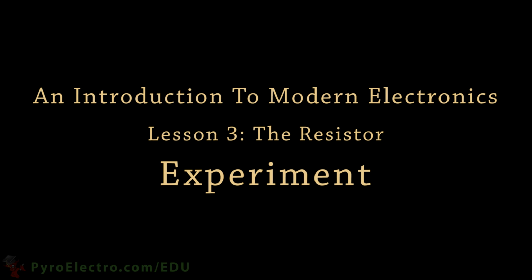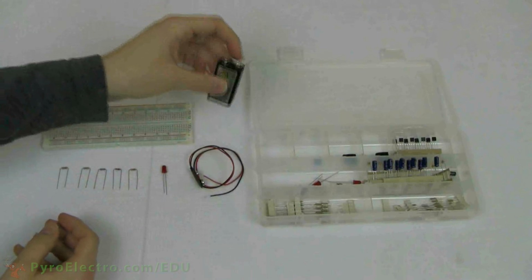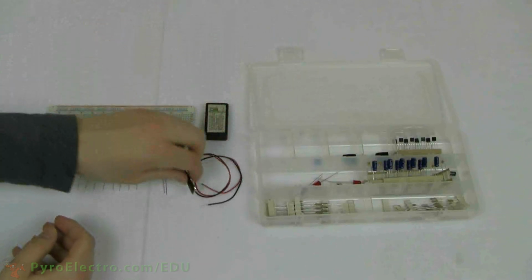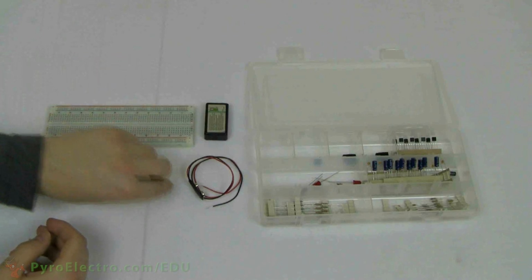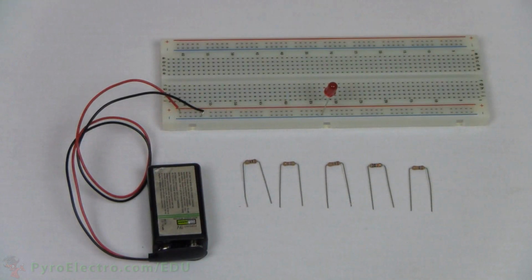Let's perform another quick experiment. You will need a breadboard, a 9-volt battery, a 9-volt battery connector, a red LED, and some random resistors from the parts kit. First, connect the 9-volt connector to the battery and connect the red and black wires to the power bus on your breadboard and the ground bus on your breadboard. Then, put your LED into the breadboard with the shorter wire connecting to the negative or ground and the longer wire going into any of the generic breadboard holes.